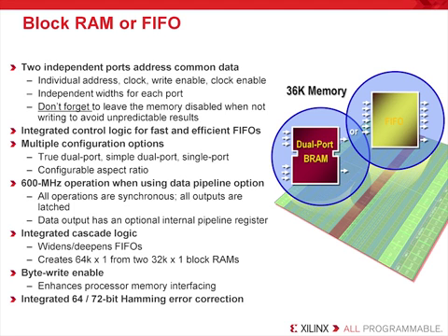It is important for you to not violate the address setup time while the memory is enabled. Leaving the memory enabled while the address setup time is unknown might produce unpredictable results. So leave the memory disabled when not writing to the memory. This will also save you power. Finally, Virtex 6 includes Hamming error correction logic to fix bit errors. We'll talk a bit more about this feature a little later.